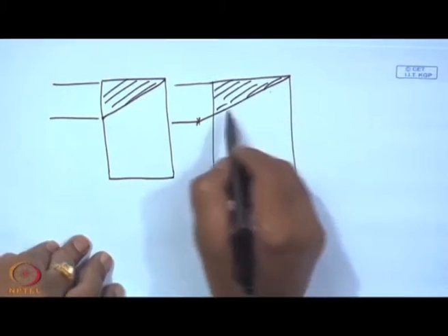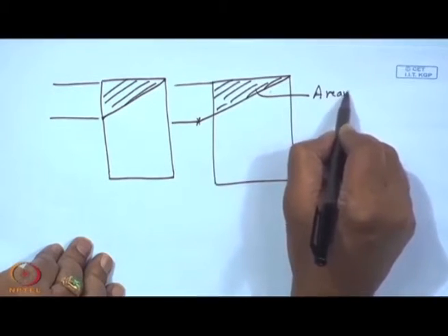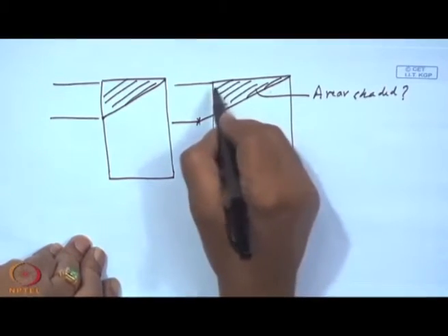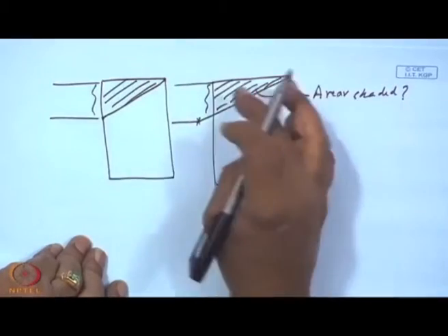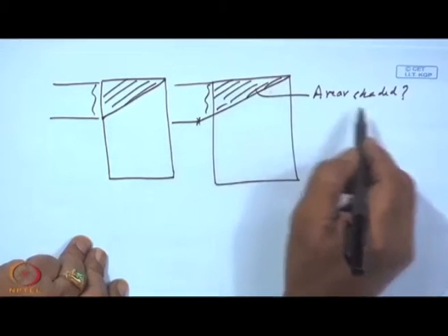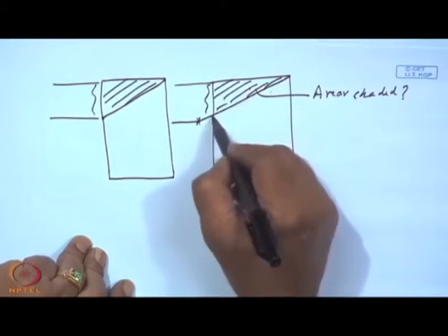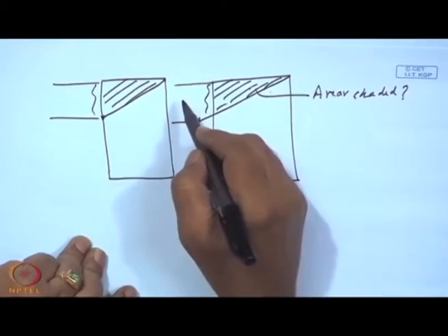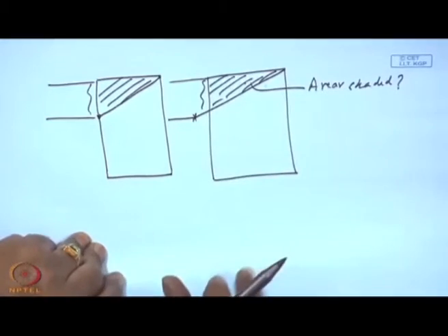So, now the problem is, what is the area shaded? So, that depends upon this or this, and in the case of a complete rectangle, no problem, width multiplied by the thickness, but we need to know whether the shadow belongs to a triangle category just ending at the edge of the window or beyond the window, or a rectangle or some sort of a trapezium like the ones we have shown earlier.